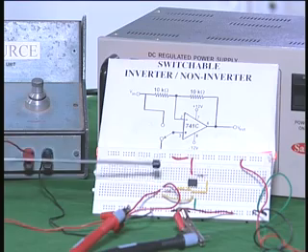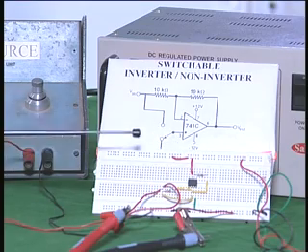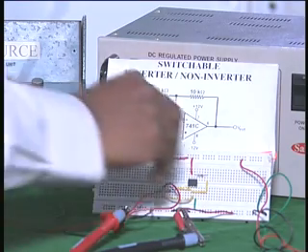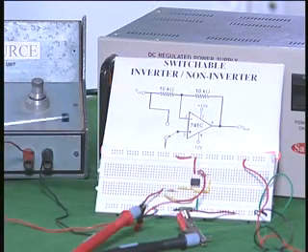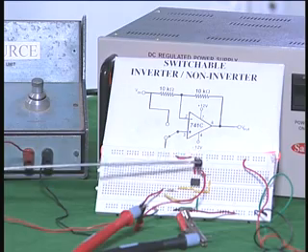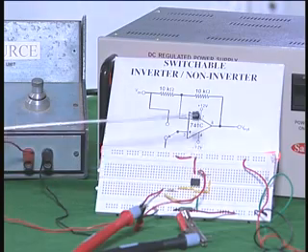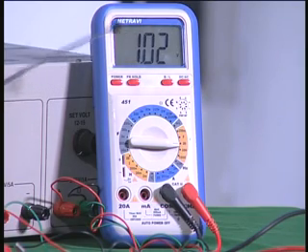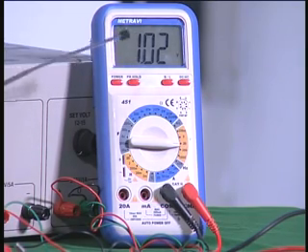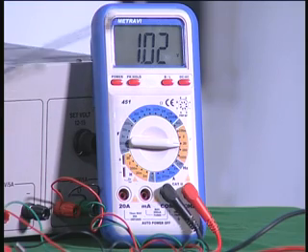Quickly I am going to take out here and connect it to the output terminal, and again I will ask you to look at the multimeter output. Now I have switched the multimeter to pin number 6 as usual, and now the multimeter will be measuring the output voltage, and the output voltage is also 1.02 plus. That means there is no inversion, and the same voltage which is given at the input is measured at the output. Therefore it acts as a non-inverting amplifier with a gain of 1.